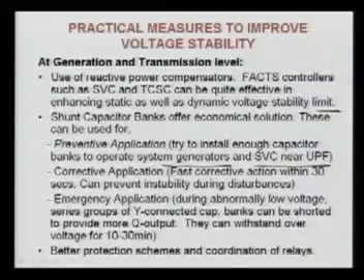If you can take action in less than 30 seconds, you can prevent the cascade tripping of the system, and therefore prevent the instability during the disturbances. That is called the corrective action. In the preventive application, you already put in enough capacitors so that your generators and SVCs operate near unity power factor, so that whenever there is a disturbance, they have more margin and can take care of it. So that is preventive.